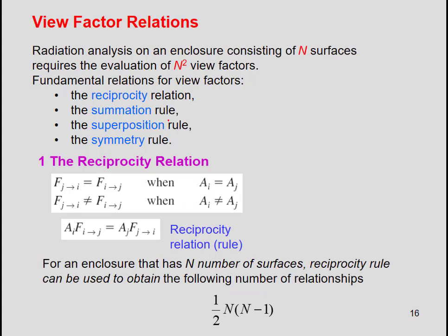And so now you can understand and calculate how much of the radiation, or how much in terms of fraction, from surface 1 will strike surface 2. Okay, and that fraction is only responsible for radiation heat transfer. For two surfaces, we know the view factor. What about when we have more than 2 surfaces, like an enclosure which consists of n surfaces?